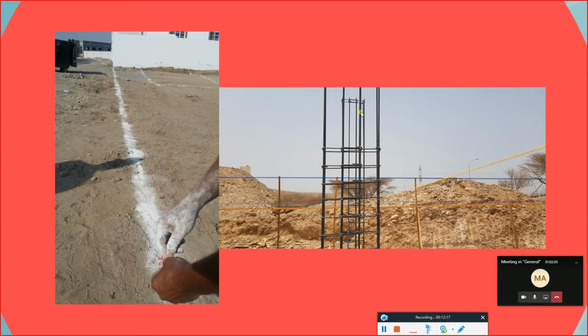By using what we call grids. When we draw our drawings in CAD or structural software like Robot or ETABS, we are using grids. Grids are the positions where normally we put our foundation or columns or beams or other elements. That's how the software understands. But when it comes to the plot, how do we understand the exact position of the foundation? It's really hard. You cannot bring your A3 paper inside the plot, which is totally empty, and ask where is my foundation now? So normally what we do, we use something called threads.